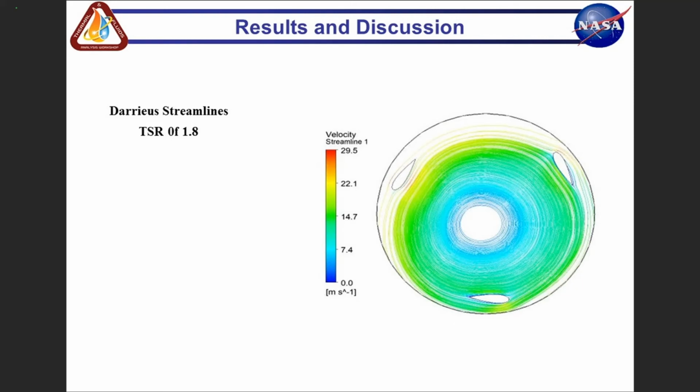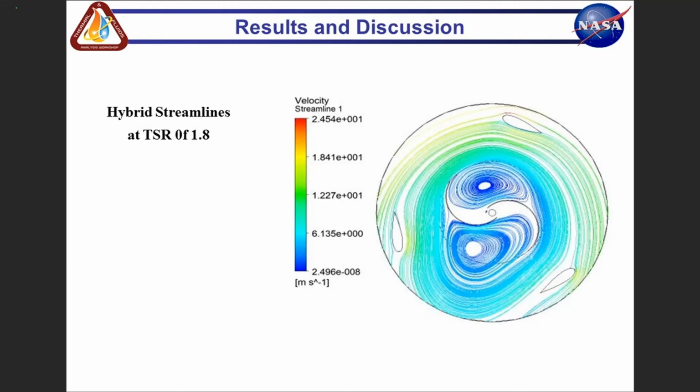This figure shows that the flow is trapped within the turbine blades, and thus results in a substantial reduction in the output power compared to the hybrid turbine. And this diagram shows what we told you here. When we compare this figure with that one, we put the Savonius in the middle of the Darrieus turbine, which blocks the flow and directs it to the side of the Darrieus blade.